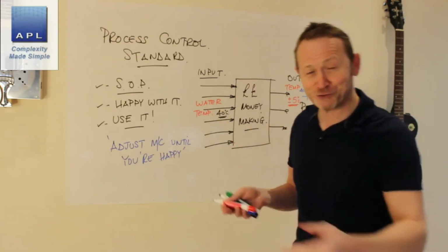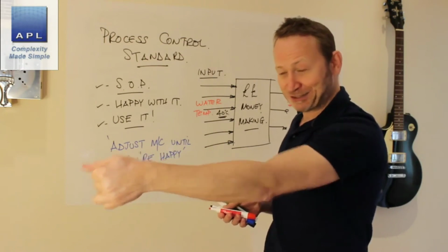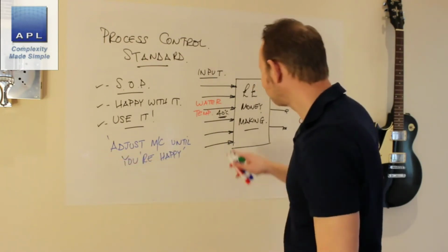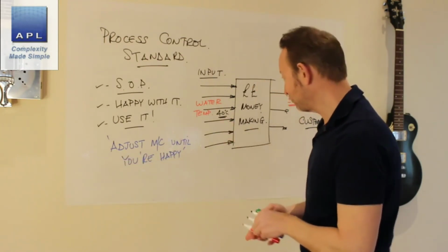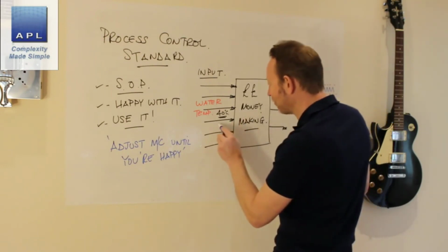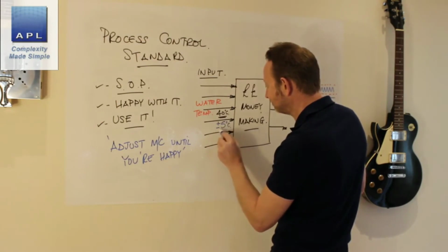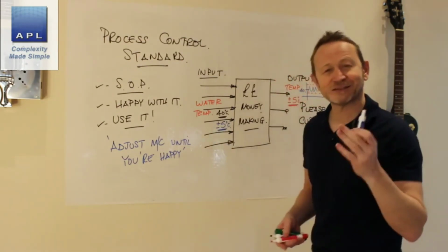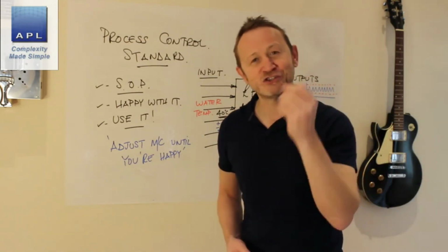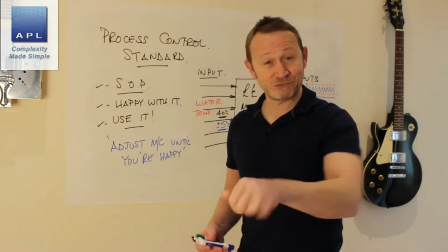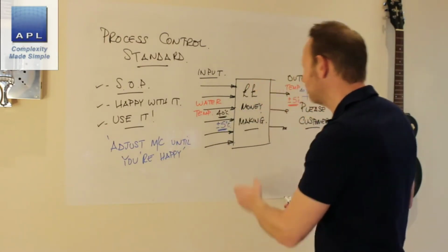He doesn't need a tolerance because he can perfectly easily dial it to 40. But now what you do is you add the plus or minus 5 degrees over here. That is a mistake. It's not necessary. He doesn't need a tolerance.